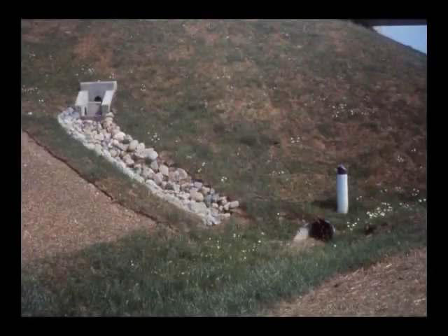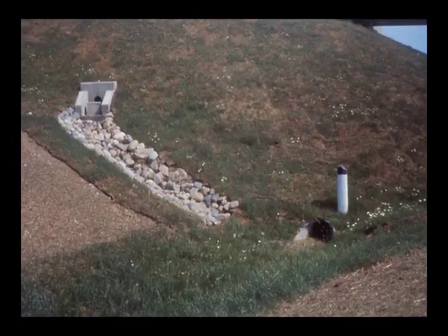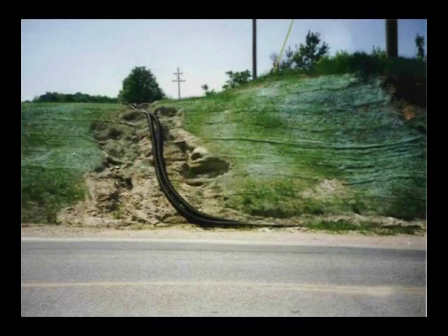Grade stabilization structures are erosion control measures that are used to carry runoff from one elevation to another and are often used in conjunction with diversions. All grade stabilization structures must be designed to carry the anticipated runoff from the site. Care must be taken to prevent scouring or erosion at the inlet or outlet, or along the side of the structure. Scouring can be prevented by one or more of the following methods.